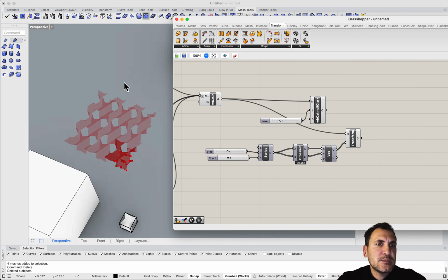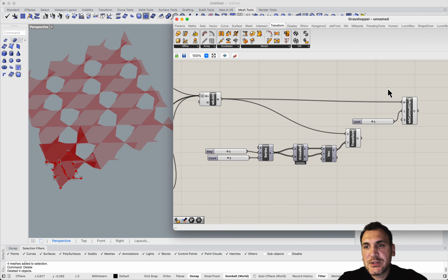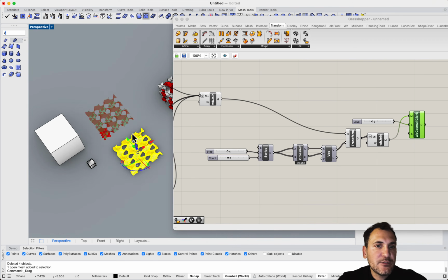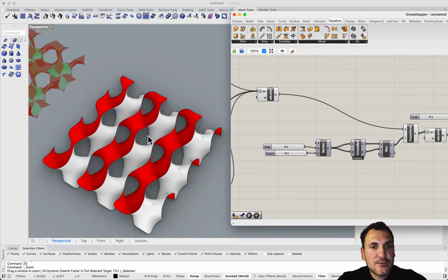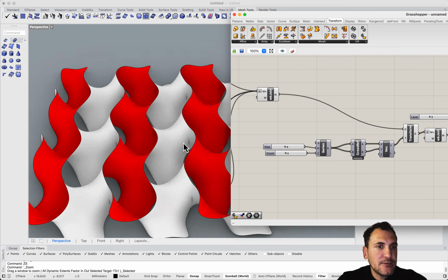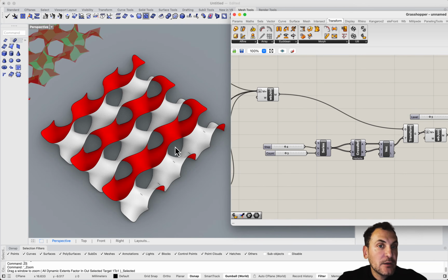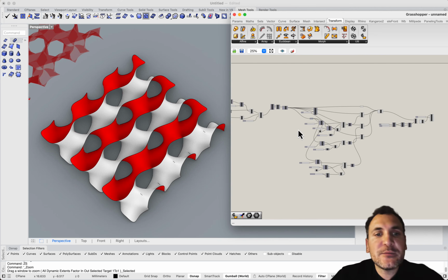There we go. So I'm making an arrayed copy of all the mesh construction, and then you can do a Weaverbird join for the final group, and then a subdivision. So once you do that, you would actually get this sort of continuous construction of the gyroid surface. I still see this seam here. Maybe it's a tolerance thing because I'm doing it on the origin. But otherwise, this is one way of parametrically constructing these minimal surfaces.